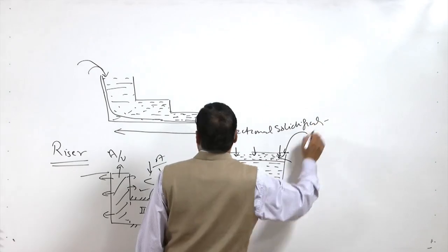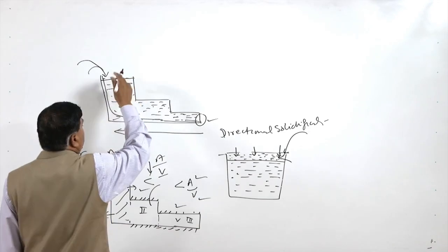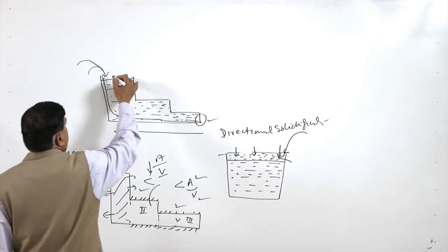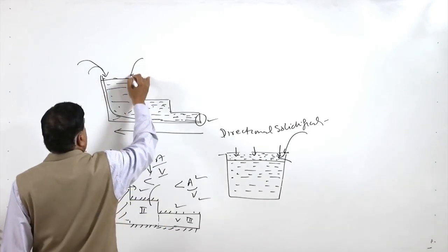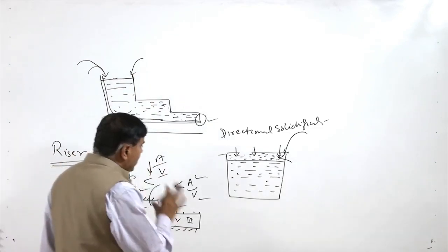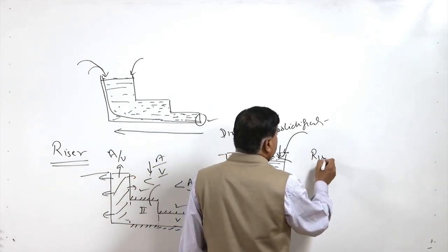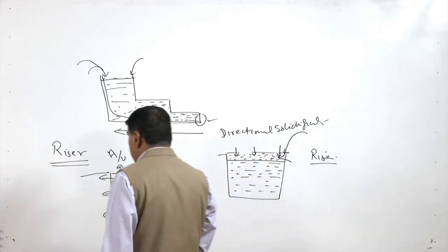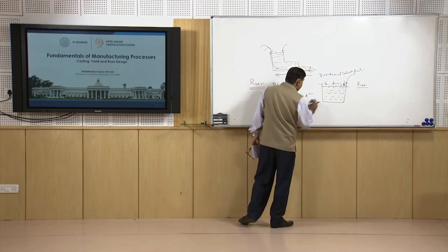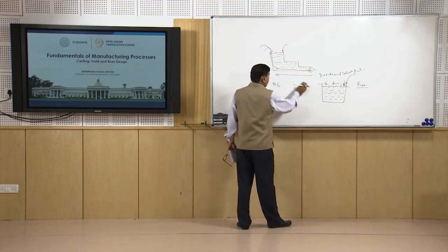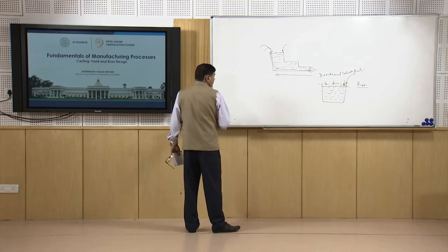solidification. And in this case, if any shrinkage occurs, then that will occur near the feeder, which can be effectively fed by the molten metal either coming from the feeder, or from the ingate, or from the riser. So, any such shrinkages can easily be taken care of by the riser if the proper temperature gradient is maintained. But in those cases where the proper temperature gradient is not maintained, meaning the solidification does not remain directional, some other kinds of issues are encountered.